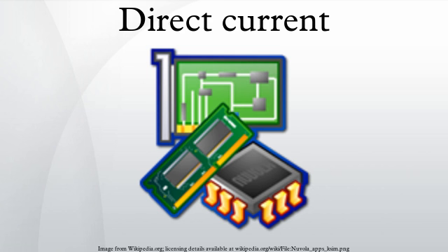A term formerly used for direct current was galvanic current. The abbreviations AC and DC are often used to mean simply alternating and direct, as when they modify current or voltage. Direct current may be obtained from an alternating current supply by use of a current switching arrangement called a rectifier, which contains electronic elements or electromechanical elements that allow current to flow only in one direction. Direct current may be made into alternating current with an inverter or a motor generator set.